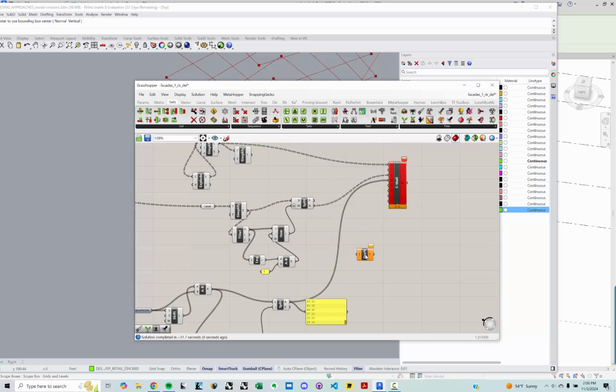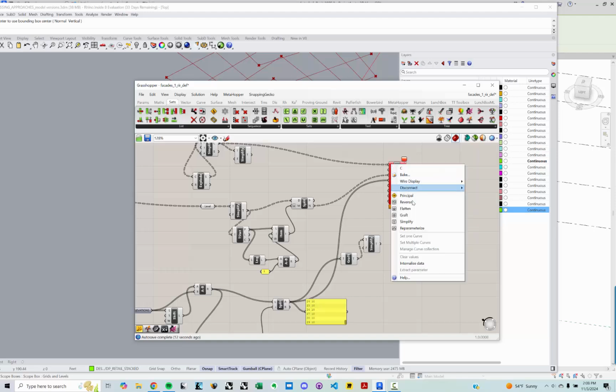I'm just gonna graft this tree because I basically want the heights to be the same in each branch. Simplify this tree. That's because I have this as a grafted list, this is a grafted list, and this is a grafted list. This is simplified, or no, simplify. This I'm gonna simplify as well. Let me unplug this first.